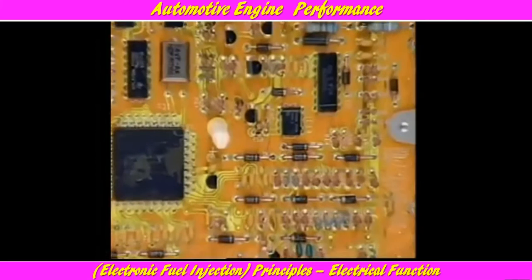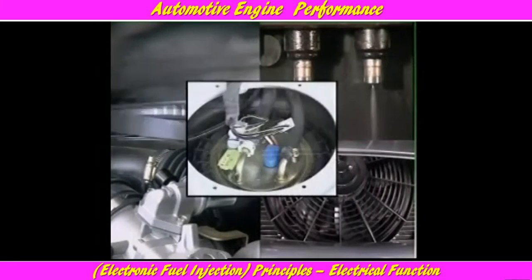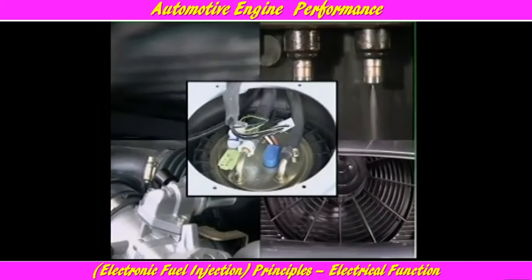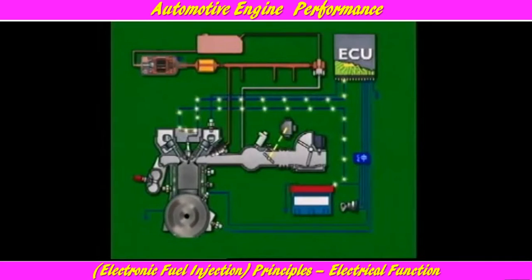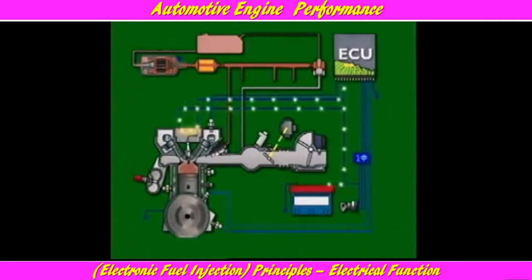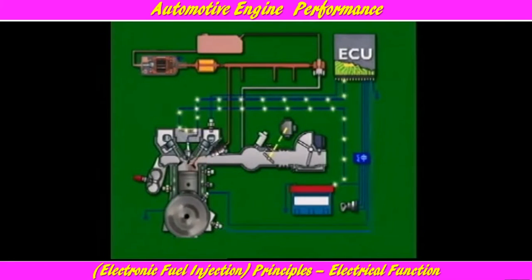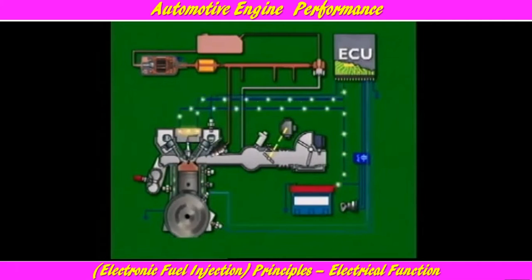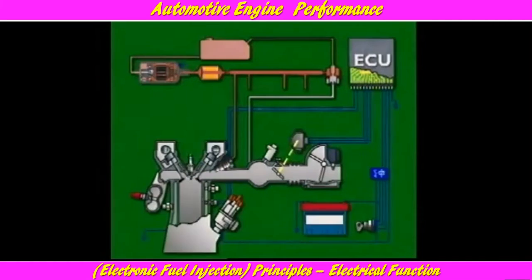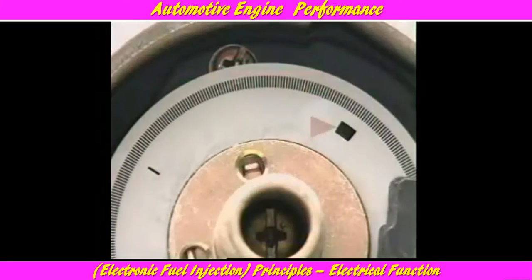In more sophisticated engine management systems, the control unit can control additional functions such as ignition timing, injection modes, idle speed, cooling fans and fuel pump operation. To do this, however, more inputs are needed. To control ignition timing, some systems replace the distributor with a direct fire ignition system. Between one ignition point and the next, the ECU calculates when the ignition point will occur. It then triggers the ignition accordingly. Ignition can be varied according to load, speed, coolant temperature, cranking speed and battery voltage.